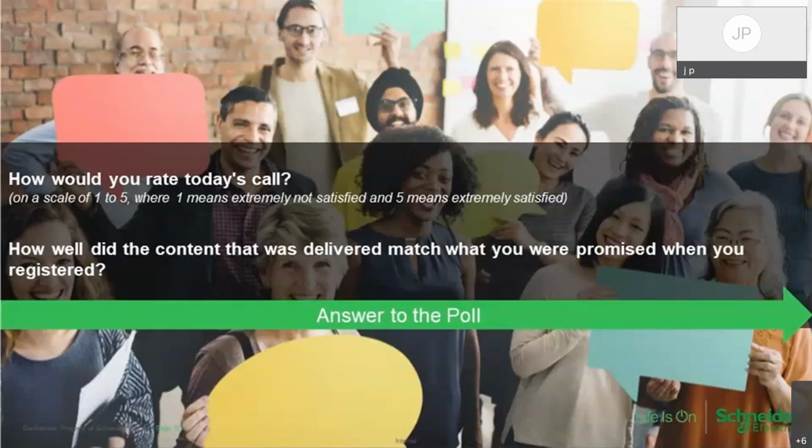In the bedroom, you are supposed to sleep, and therefore you are not able, in some cases, to wake up and escape from the fire. So this is why we nowadays push for the time being a recommendation, and we are going to push for a mandatory use of arc fault detection devices in order to avoid that a fire could start on the electrical installation.